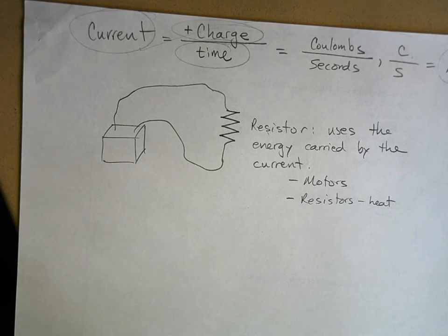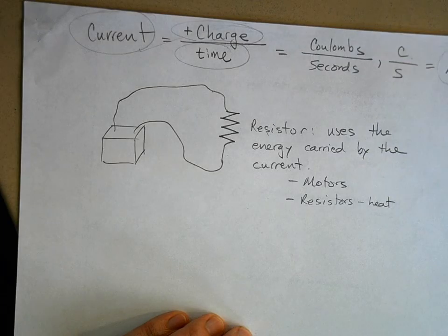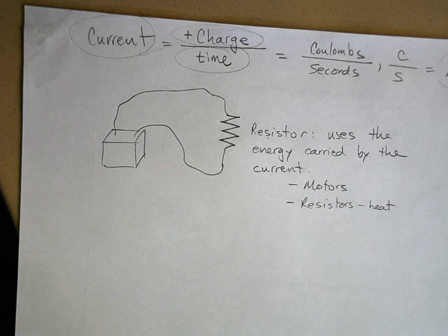What? You get magic smoke, because now the wires in that motor become like a resistor, and resistors give off the energy in the electricity as heat. If the heat gets really hot, the insulation on the wires of the motor will literally burn. Burn, baby, burn, and give off smoke. And that's when you're destroying your motor. Yeah. So hopefully that doesn't happen.